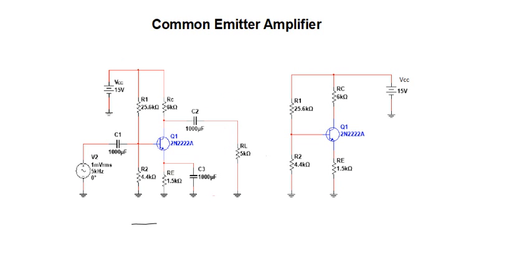So we draw that, and we got a small AC going in, and hopefully we'll have a great big AC coming out. Now, there's limits to that. I can't go over that 15 volts. In fact, remember we got to bias and have our operating point or quiescent point up in the middle of that 15 volts. So we could probably go +7 to -7 as an output with this particular setup.